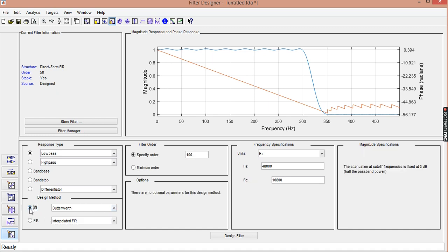If you're going to use IIR, then if you remember in your DSP courses, the infinite impulse response filter design is primarily based on analog filter design. So you are looking at Butterworth, Chebyshev, elliptic filters. These are analog filters, and then from bilinear transformations or other S to Z transformations, you transform these to digital filters. Okay, so primarily you are designing in the first place an analog filter if you're going to design an IIR filter, and then you are going to transform it. So you don't have to do anything. If you're going to select an elliptic filter, just give the specifications. Design the filter, bring the coefficients in the workspace.